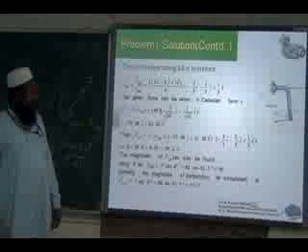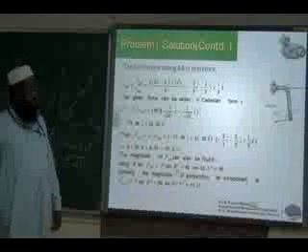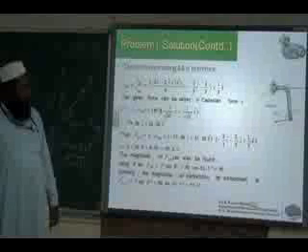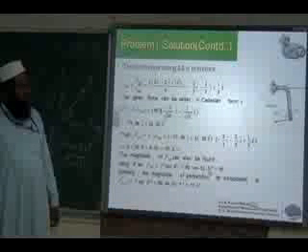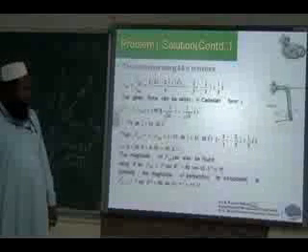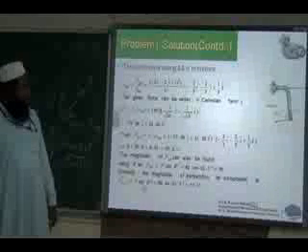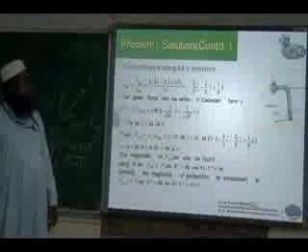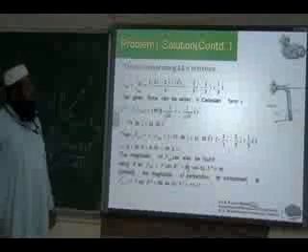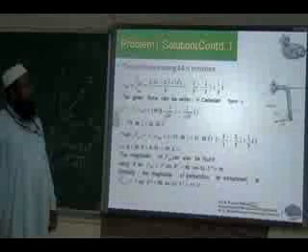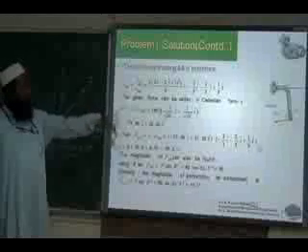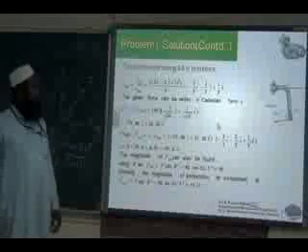So magnitude for FPA can also be found using theta. Cos theta concept. Okay, so F cos theta is 80 cos 42.5, this is also 59. So perpendicular component can be used. Theta is known, we can use F sin theta and find the magnitude of perpendicular component. So we apply the dot product concept to get the unknown angle as well as resolving the two forces. The application is completely illustrated in this problem.